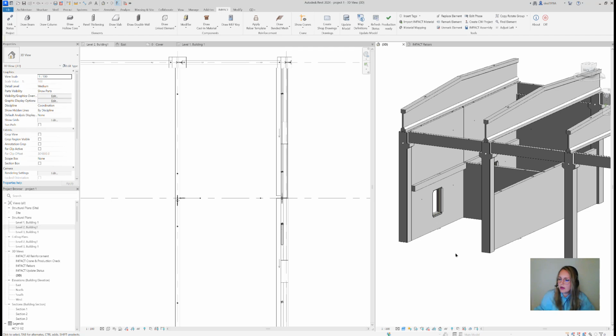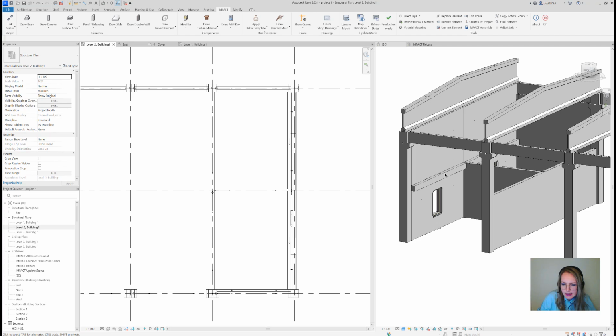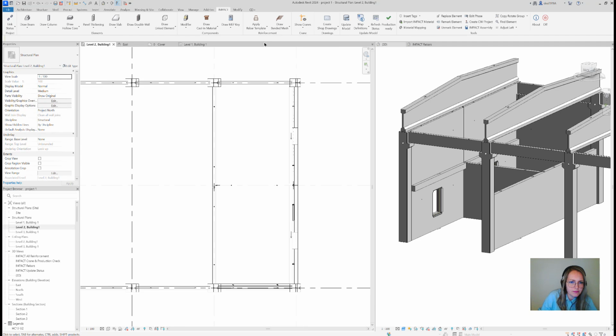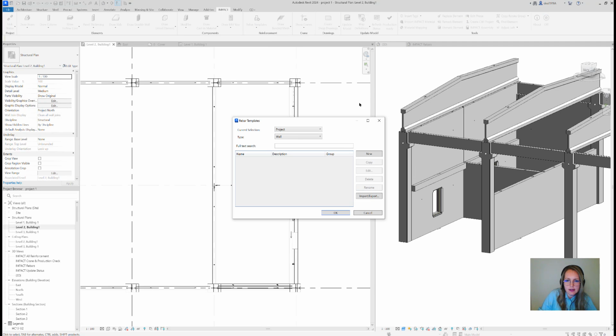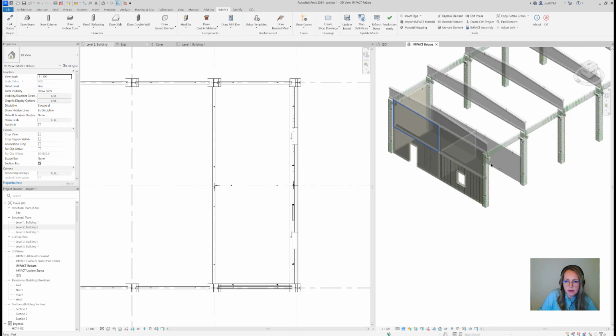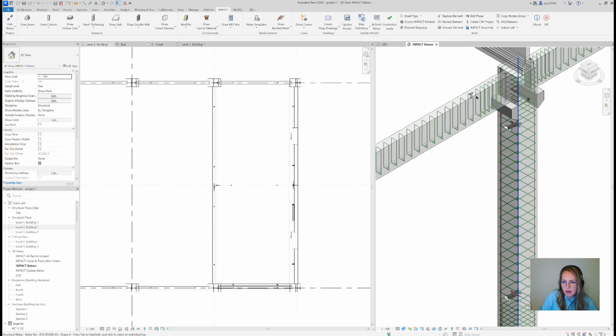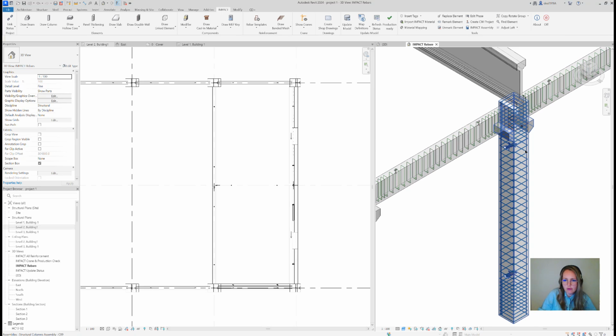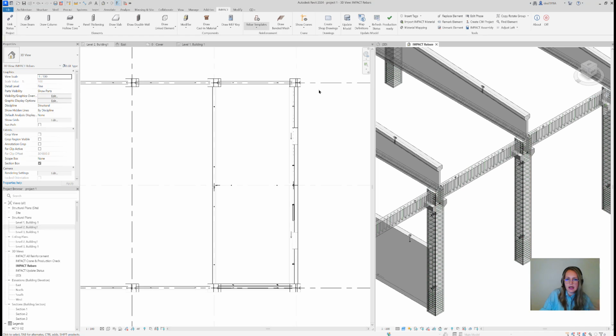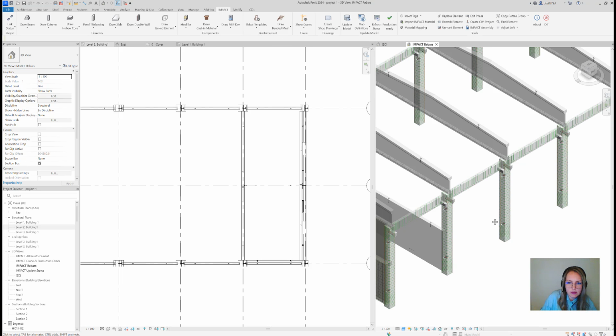Now, I want to show you a rebar functionality together with the panel thickening. And what you can say about the panel thickening is that it's one of the many components where you can add the rebar templates. So first of all, the rebar templates is something I demonstrated last time in connection with the columns and beams. So each one of these rebars, they are actually added with the help of the template. So you save the combination of these rebars in a template, and you can just apply it to the same family. The same you can do with the panel thickening.